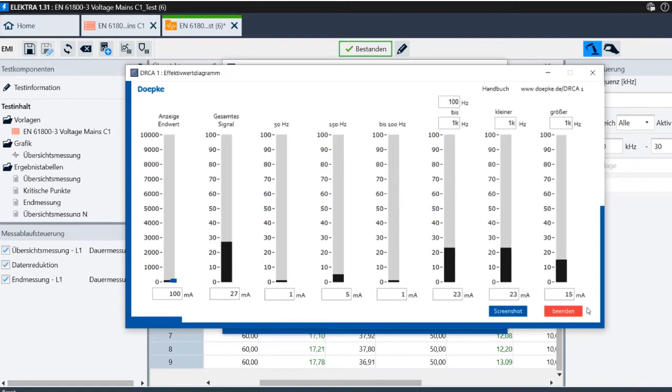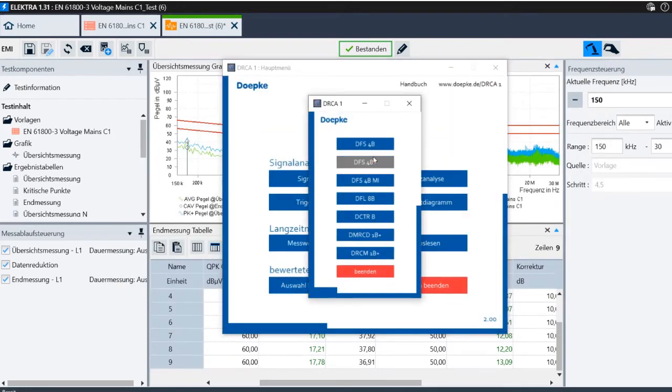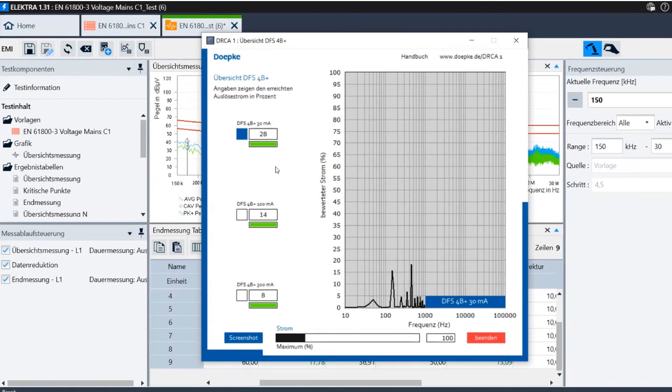And also for the higher switching frequencies, it's always the same. So it will be reduced because the filter attenuates even better for higher switching frequency or higher frequencies close to the resonance frequency of the filter. And here we also see that we have more or less the same amount than before for the RCCB in percentages.